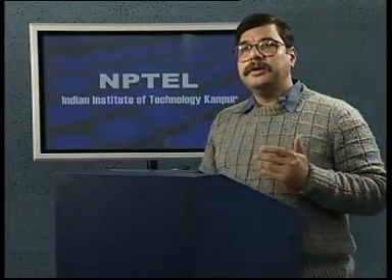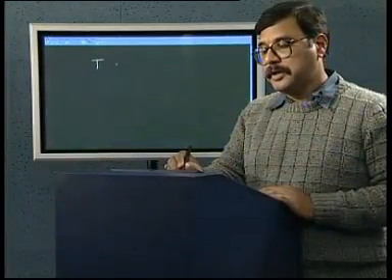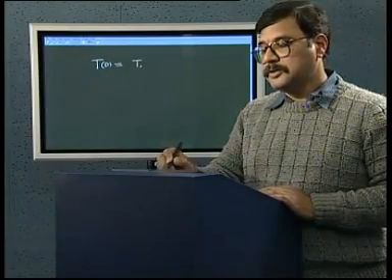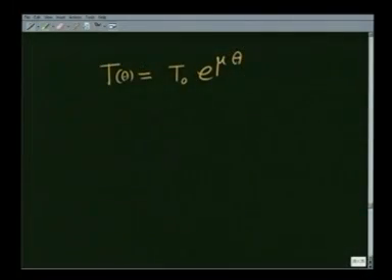Suppose you tie a rope or a clothesline in your backyard. You generally put it on the nail and wrap it around a few times. You are unconsciously using the fact that tension as angle goes up goes as T0 e raised to mu theta, so that with a very small force on one side you can balance a large force on the other side.